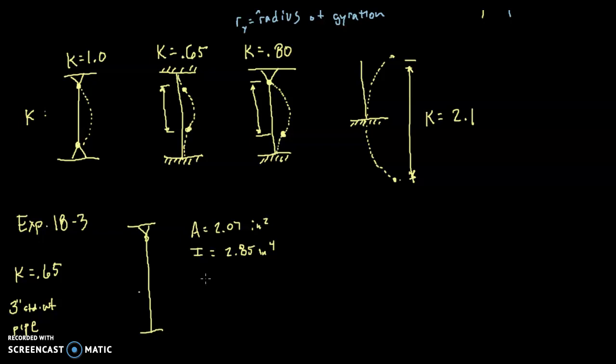If we were talking about a wide flange, it would have two distinctly different moments of inertia. And radius of gyration, same thing. There's only one radius of gyration given, and that is 0.791. No, I'm looking at the wrong row. That's for a 2-inch pipe. 1.17 inches. The unit for radius of gyration is just the inch.